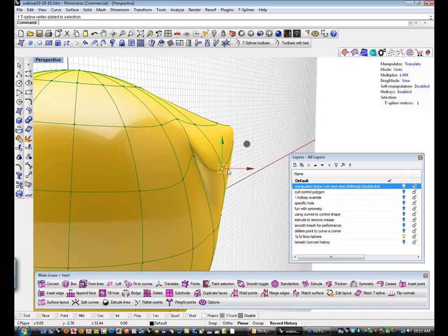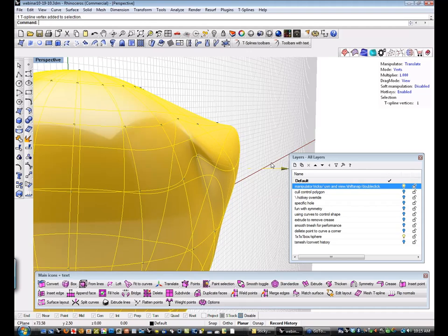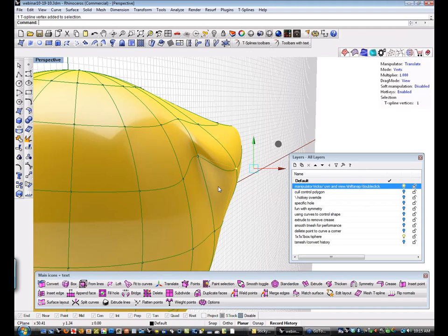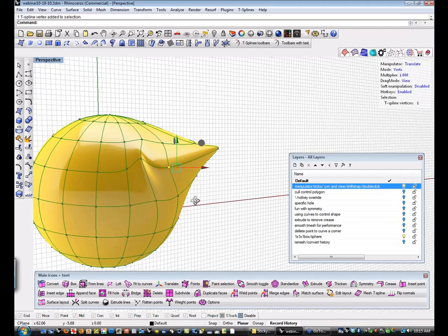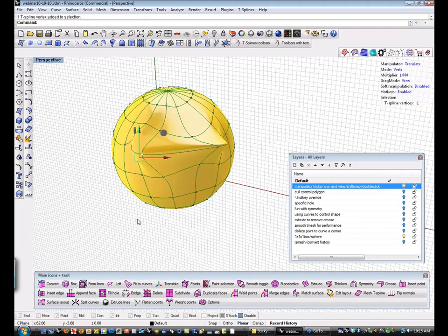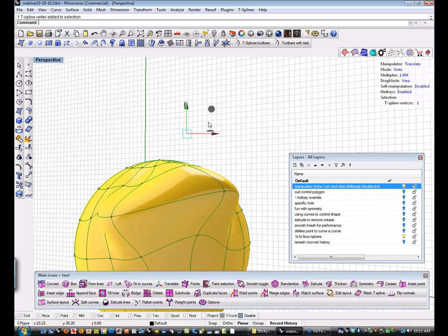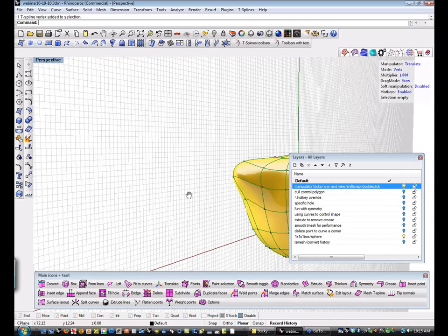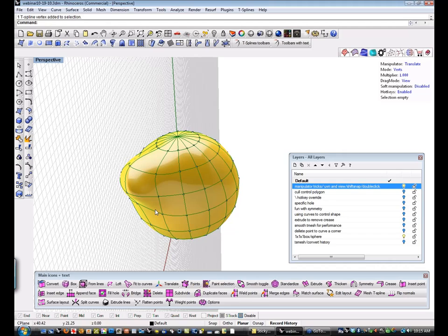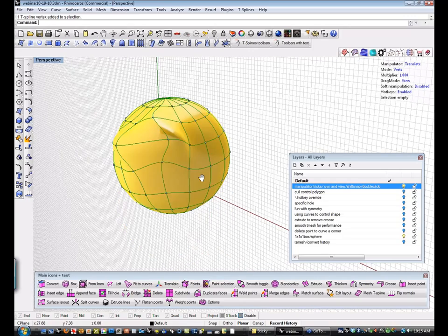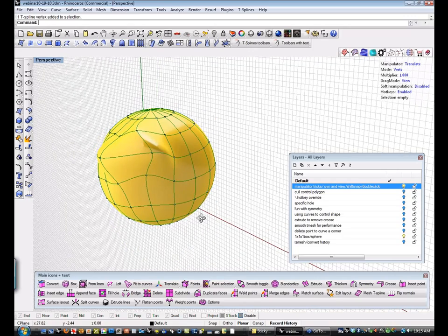Now, obviously, you could go in and set up a construction plane based on the coordinates of that unit, but view is a really quick, simple way to go in and grab something and manipulate it. Not as accurate as the world views, but it's really quick, especially if you're sculpting something that's fairly organic, which, let's be honest, that's what T-Splines is all about, right?